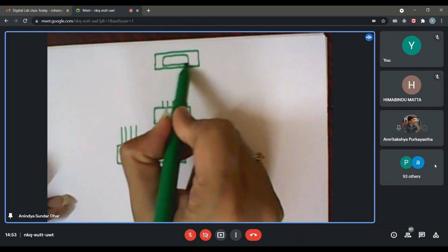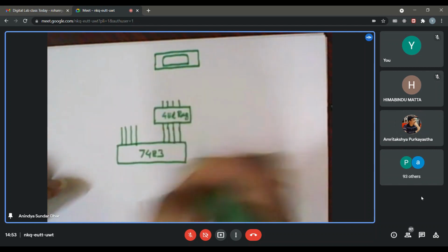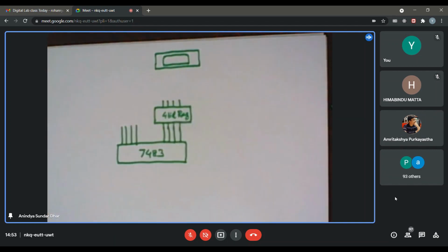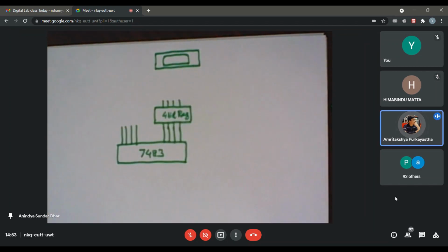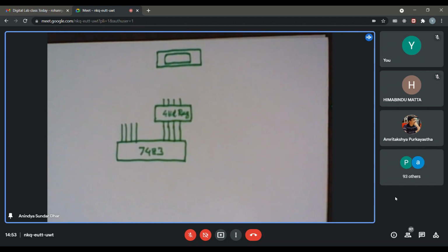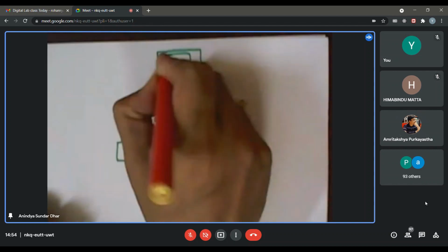then how do I make the rest of the circuit understand that I have pressed a new key? We use the strobe key, strobe output. Right, but that hex keypad, at least whatever is available in the simulator, doesn't have a strobe key. So what I can use as a substitute is that ASCII keypad over here.